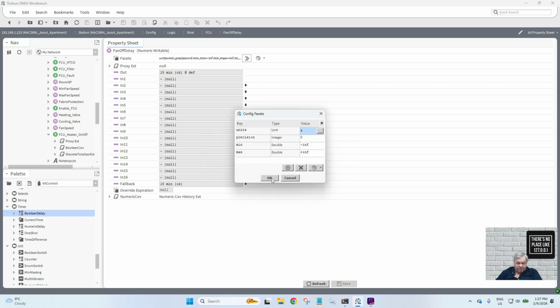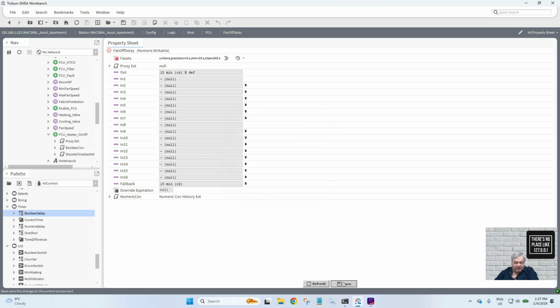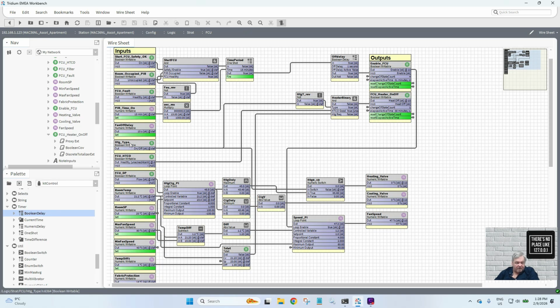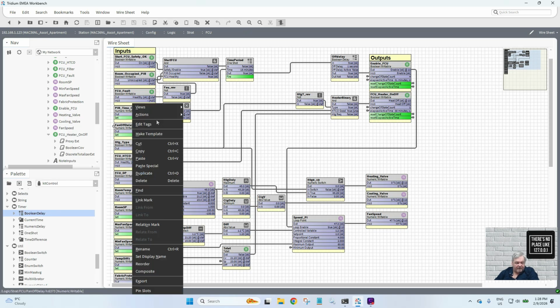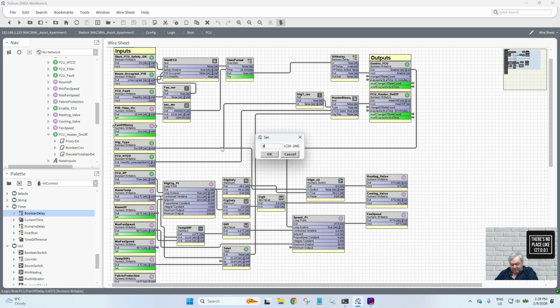Okay. And I always want an off delay. Well, I put 10 seconds, so it's always going to be, no, I can't put it to 0. And we'll put that to 60, 120, 240. Not that they would actually run it at that. And at the moment I have got 15 seconds off delay. I would actually set that to 30.